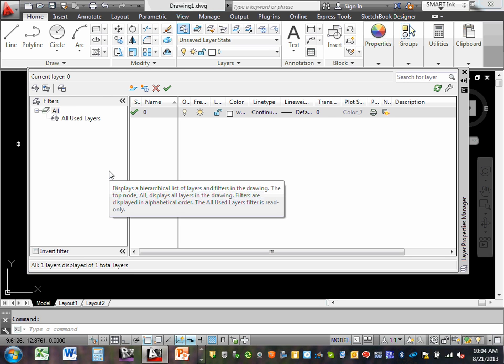So when you bring all your architectural stuff, you bring in one layer. You grab it, you put it behind the window. So here's the layer related to architectural. Then you put all your electrical on the window here. That becomes another layer, separate from your architectural. What this does for you is you can turn things on and off without damaging the original one. It's like this will be your architectural in one layer. Then I'm going to turn everything off on this layer here. Turn it off, but this one will continue to be on. You'll see it's very, very powerful. So that's what we use there to turn things on and off, control what we want to print, control what we want to see.